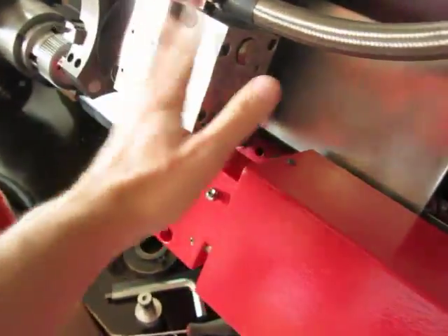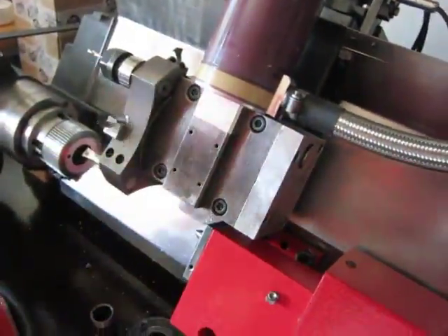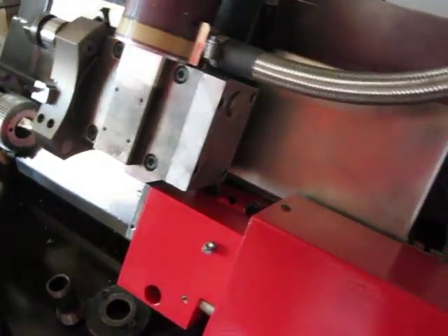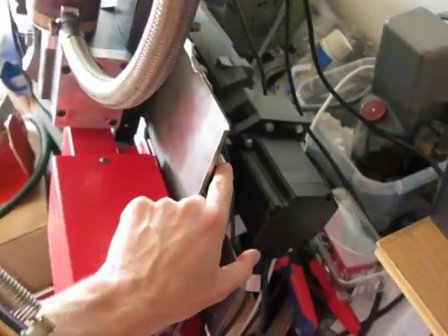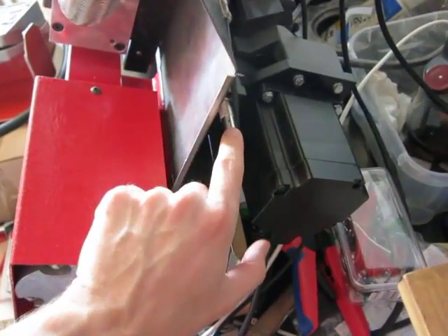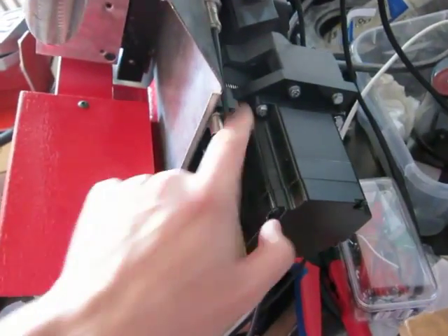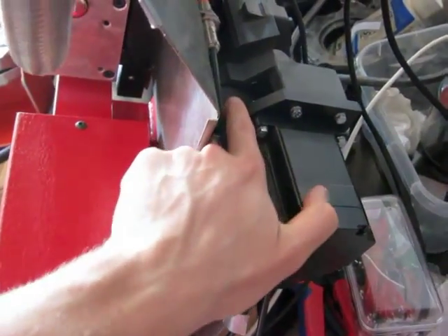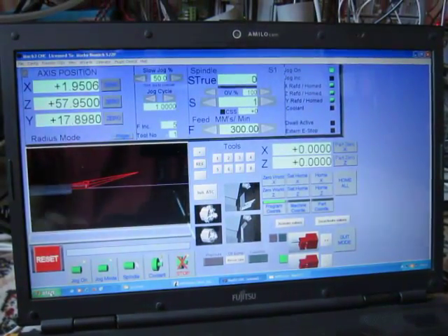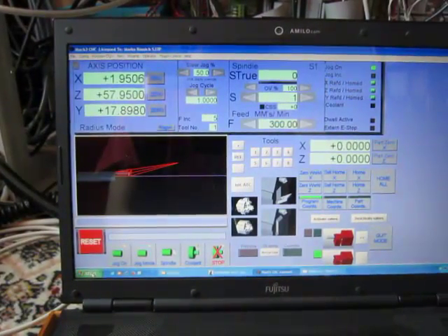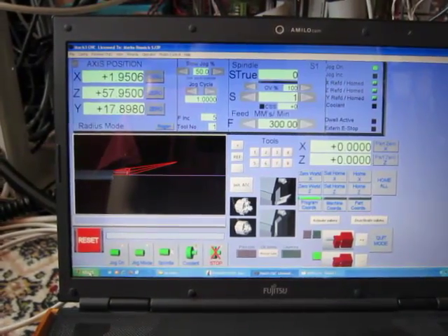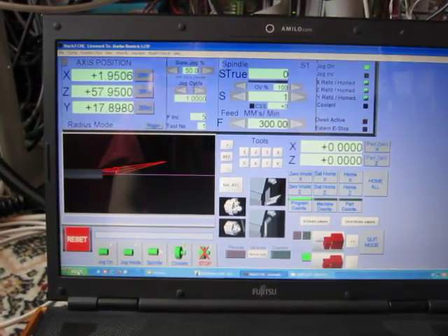So when this is moving in the z-axis left and right, this sensor detects impulses, and after 4000 impulses the oil pump should be turned on for 20 seconds.